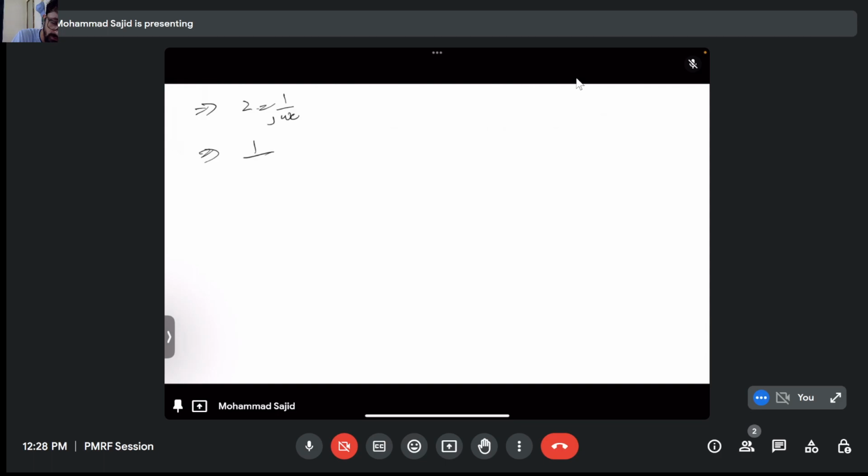The omega cancels, and we'll say C Miller in will be equal to C times 1 minus AV. So this is how you get this formula.